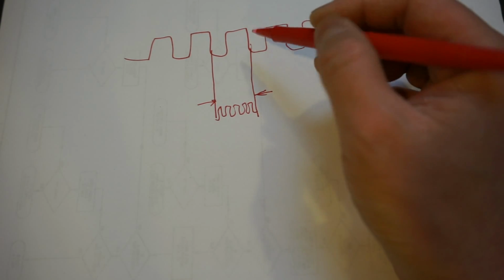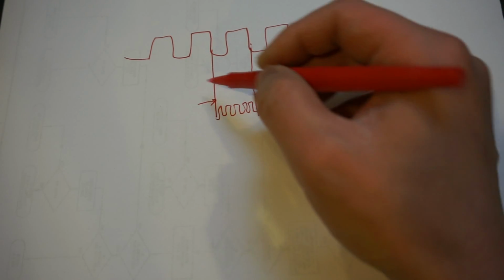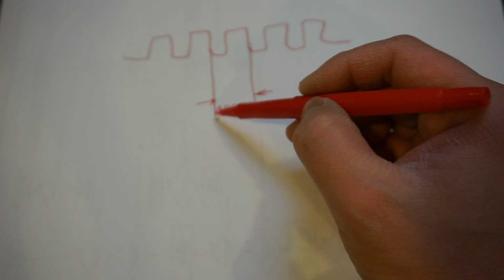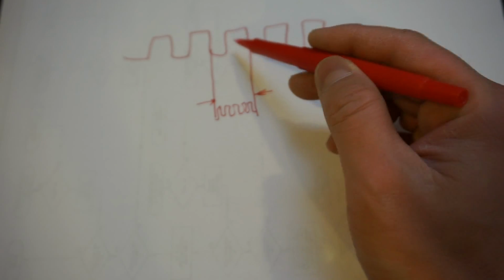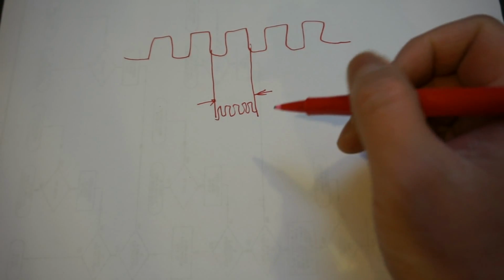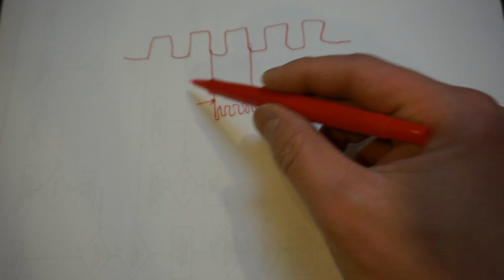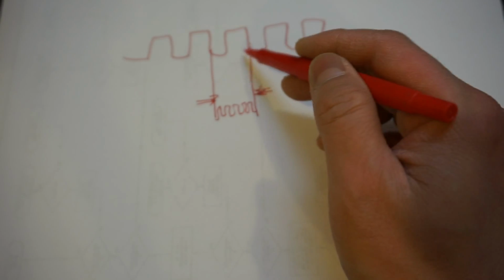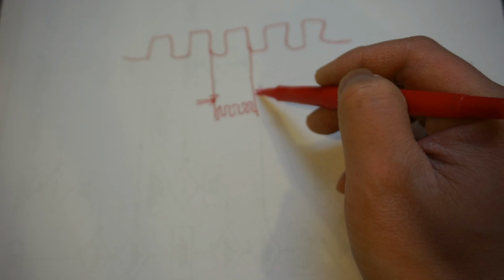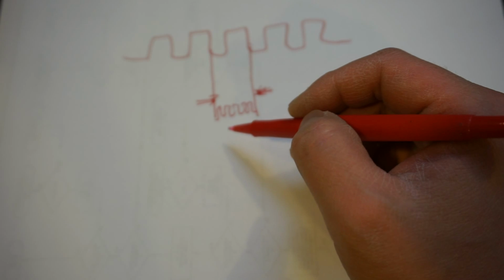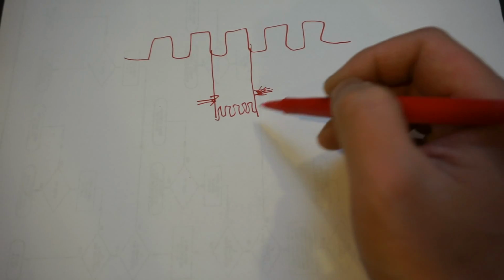can be ignored. Of course, we still have that plus and minus 1 error, because the clock here is free running, and it depends on where this incoming pulse starts. You might be counting 1 less or 1 more of your clock signal. But for a given time period, whether the input is 1 pulse or multiple pulses, as long as this time interval is fixed, our plus minus 1 error is precisely the same and can be predetermined.